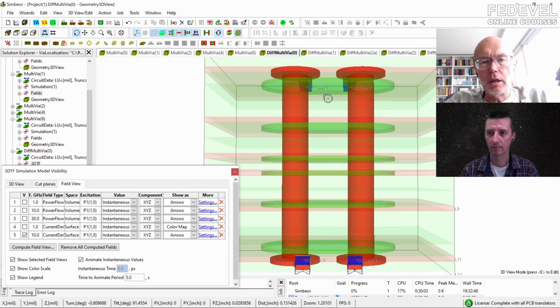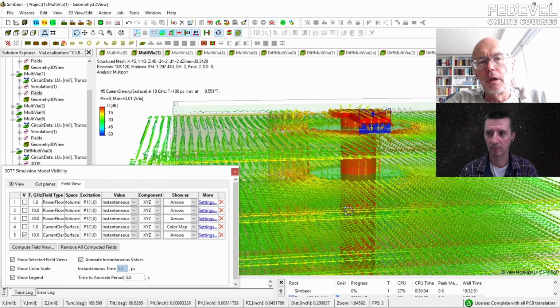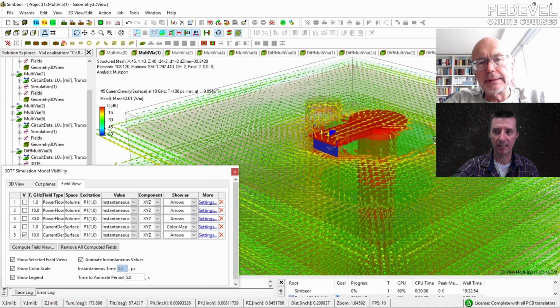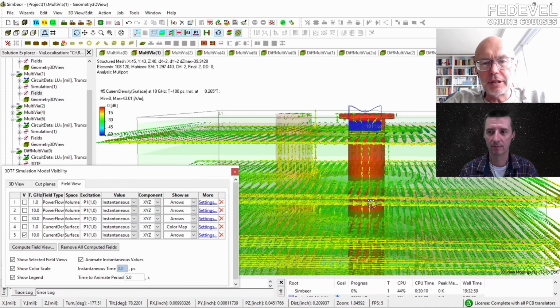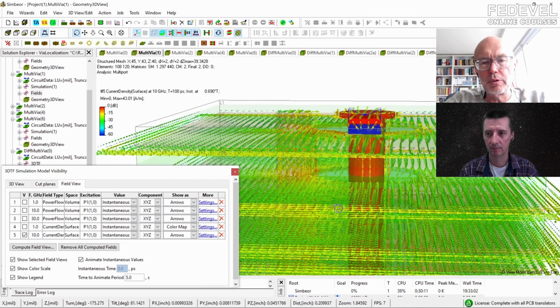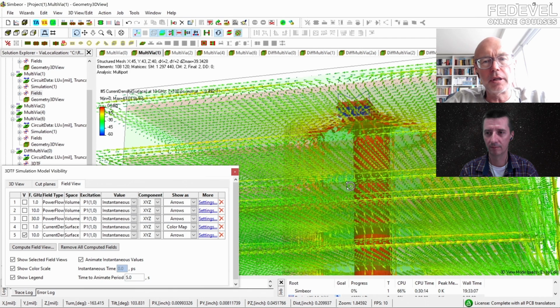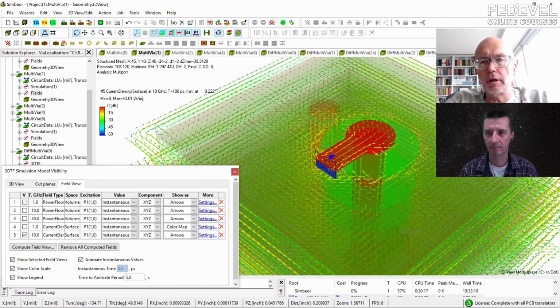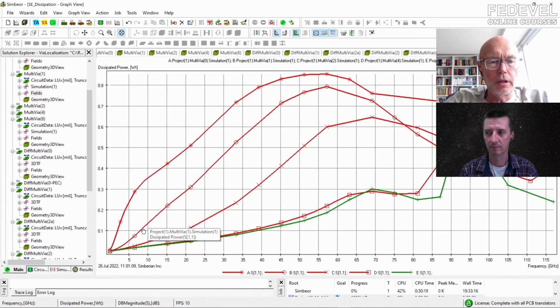So in case of this via, this via is not only the via, but it's basically also all the planes which are connecting the via. That's the problem. All the planes, and the current has to be redistributed at every location. And technically, this structure has much smaller bandwidth. Again, if you compare the dissipated power for single-ended, this one is with one stitching via. At 0.2 or 20% loss, we have 14 gigahertz bandwidth.